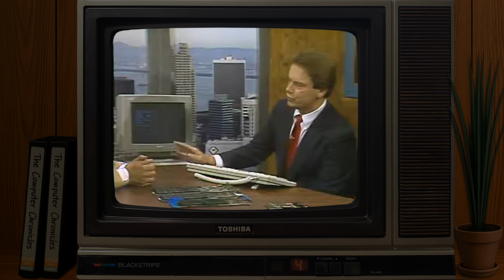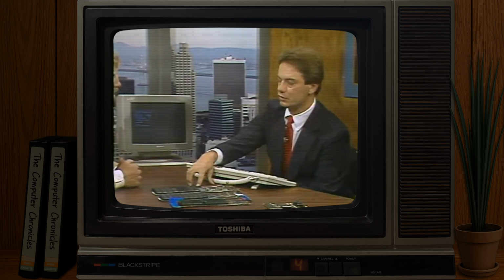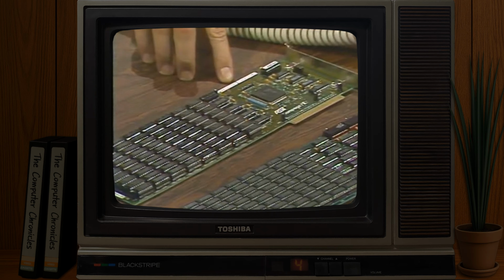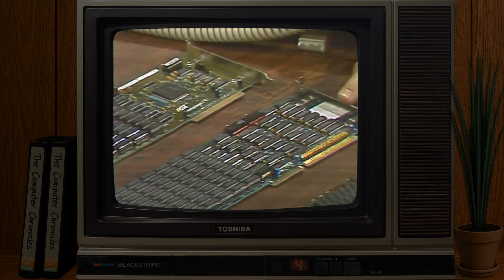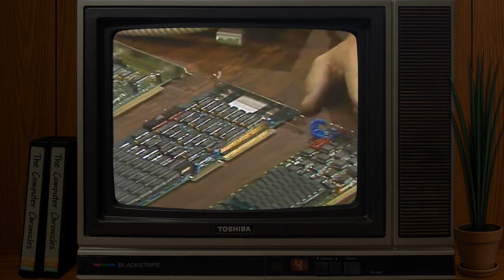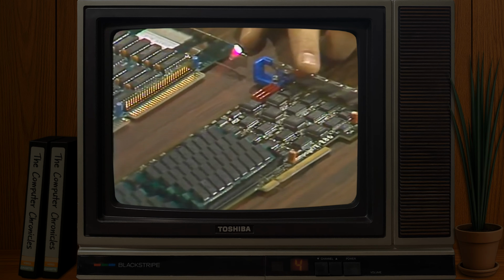Okay, tell us about this board now. Sure. What we're going to be showing with the Premium 286 is an expanded memory computer, but we wanted to emphasize that it's not simply a function of the computer itself we're using. We also have boards that span the entire range of processors and bus types. For example, for an 8088 machine, a PC, XT, or even the Model 30, the 8086, there's the Rampage 2, which is a 2 megabyte EMS 4.0 memory board. For 286-based machines and compatibles, we have the Rampage 286, and for the Model 50 and 60, for the PS/2 line, we have the Rampage 2 286. All three of them provide 2 megabytes of memory.